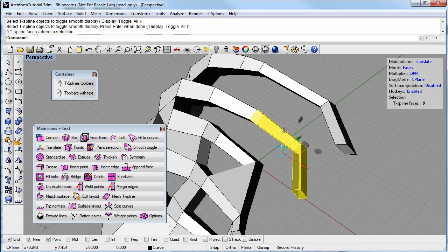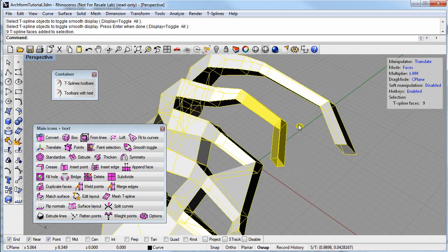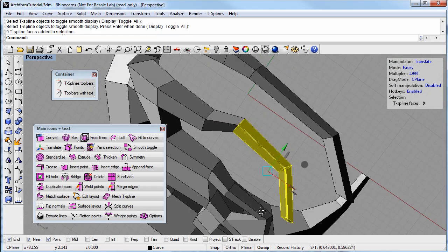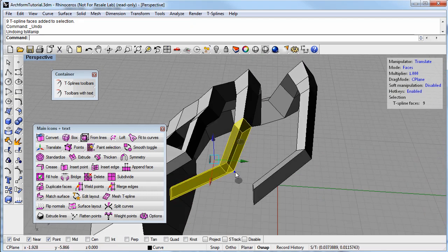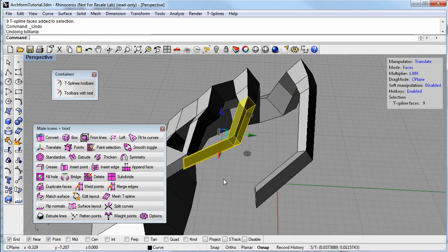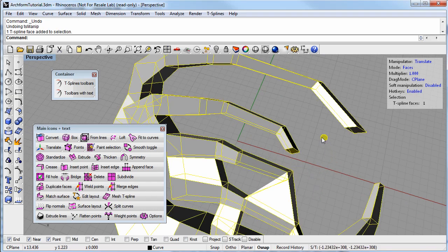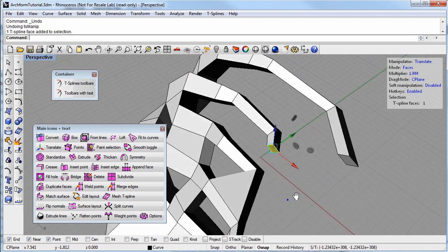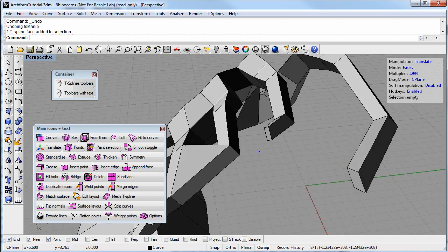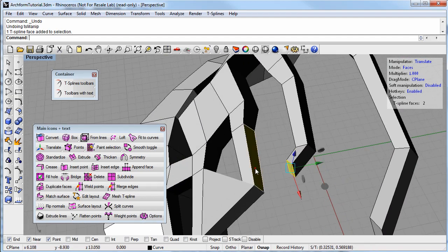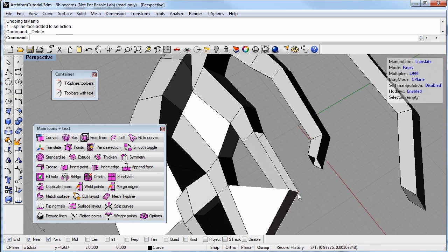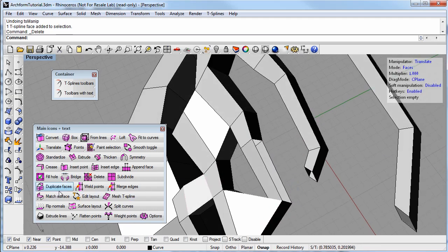You pull these faces in over here. Move this guy. I think in this case the weld's giving us something that we like better. So I'm just going to do that again. So select these faces, hit delete, and then just weld these control points together.